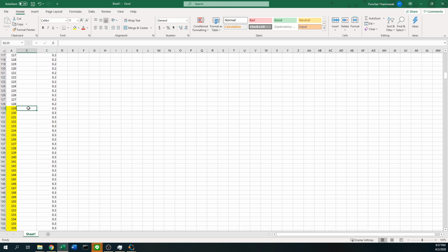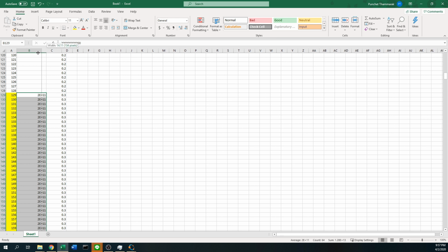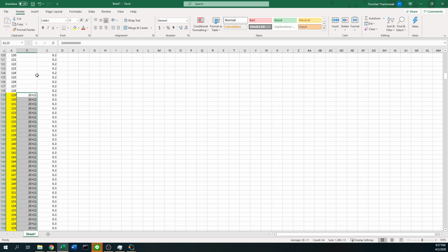Okay. And how about the modulus? Elastic modulus for steel is going to be 200 gigapascal. Giga means I'm gonna have 9 zeros. Hit Control and Enter, then you get 2e to the 11th, 2 to the power of 11, and this is acceptable. MATLAB, or Octave, is going to understand this.